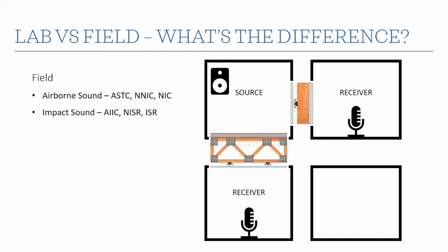Impact sound, we have a similar situation, three different metrics: AIIC, NISR, and ISR. And again, they're all measured the same way with the tapping machine. It's just room conditions and things like that that differentiate between the different metrics.